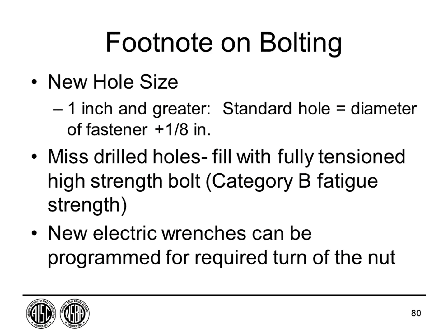For bolts less than 1 inch, it'll be the diameter of the fastener plus 1/16. This is being done because there have been problems with the larger diameter bolts, which are typically hot forged bolts. There's a forging seam, and they're not as round, and they won't clear a normal 1/16 inch hole. So this was to prevent that problem.